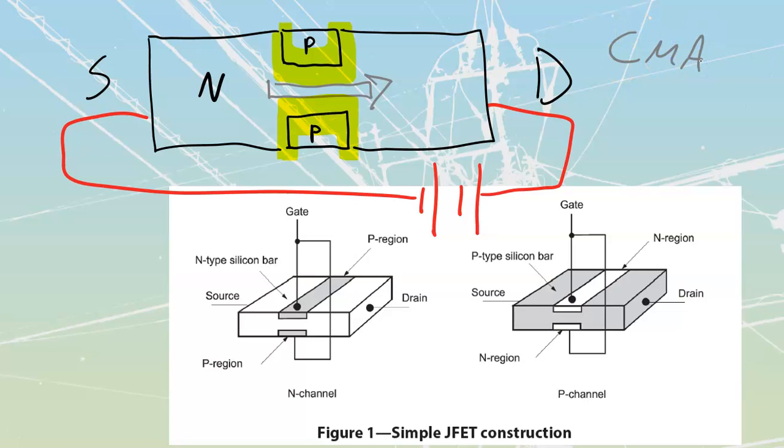If I take this now and reverse bias, I'm going to take a negative over here and attach this to my N type of material. Well, if I've got a negative, that means I've got an excess of electrons inside of here. Those electrons are really going to fill the holes in my P type of material, right? So we've got some holes inside there. We're going to get electrons that are going to flow into here. There's going to be a small amount of initial current flow just to set up these depletion regions.